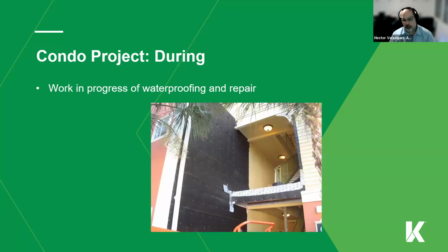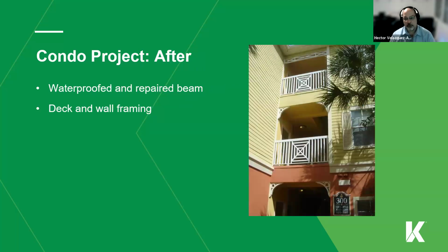Doing my paper-backed glass, doing my Tyvek or my waterproofing system on a wood frame wall is a lot better, and lap it properly. You try to avoid having a joint right at the corners. Try to go past the corners or before the corners so you don't get those issues. Those areas are critical for everybody.